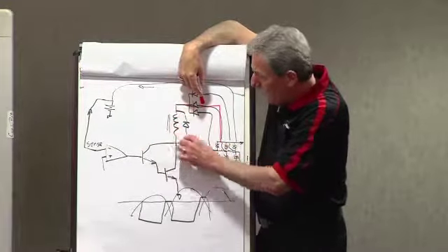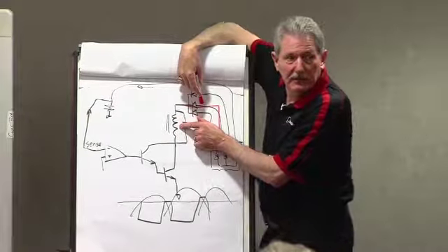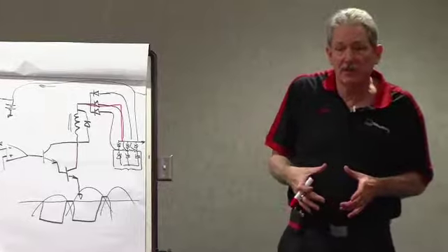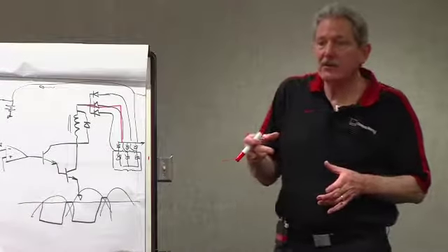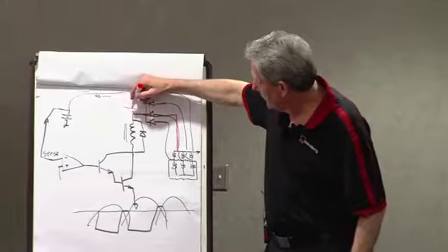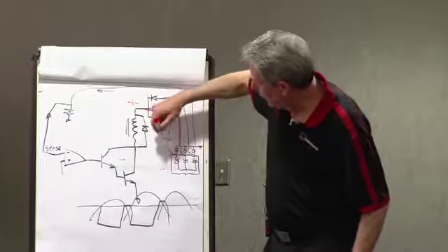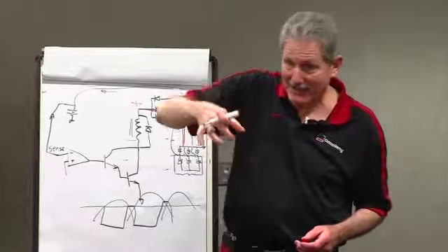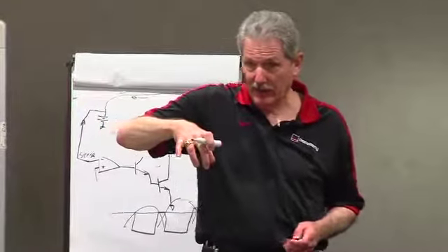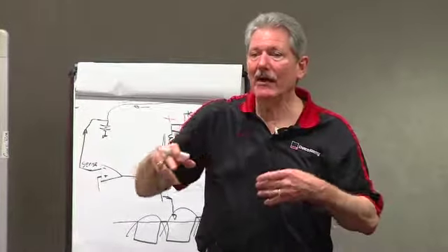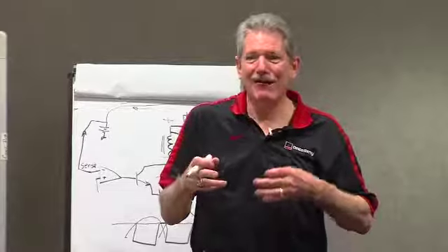So all around the field is surrounded by ground because the alternator is at ground potential. So now there is a possibility of having corrosion because I have a positive voltage here, negative everywhere. So with moisture, remember the slip ring interface is copper, carbon, potential, medium. Now I have corrosion. I have galvanic cells.